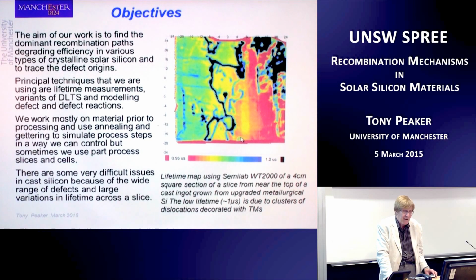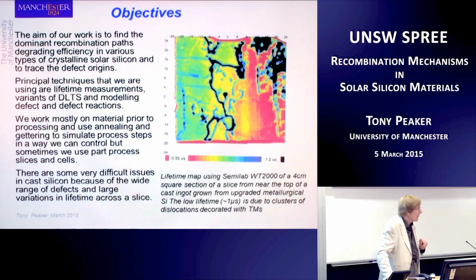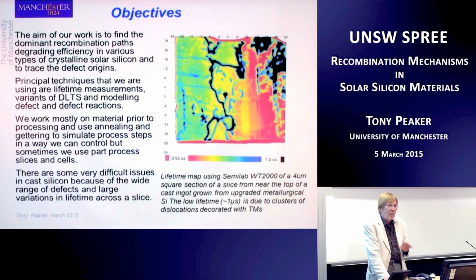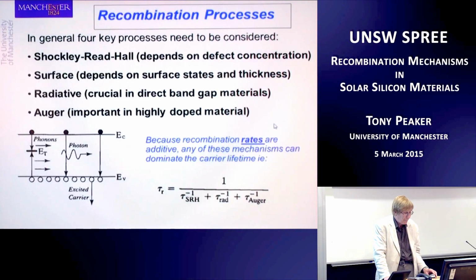This is about a microsecond lifetime. It's made from upgraded metallurgical silicon, and it's from the top of the ingot where there are loads of clusters of dislocations, and there's also loads of transition metals. So everything you could imagine is wrong about this material. And measuring it and assessing it is very, very difficult.